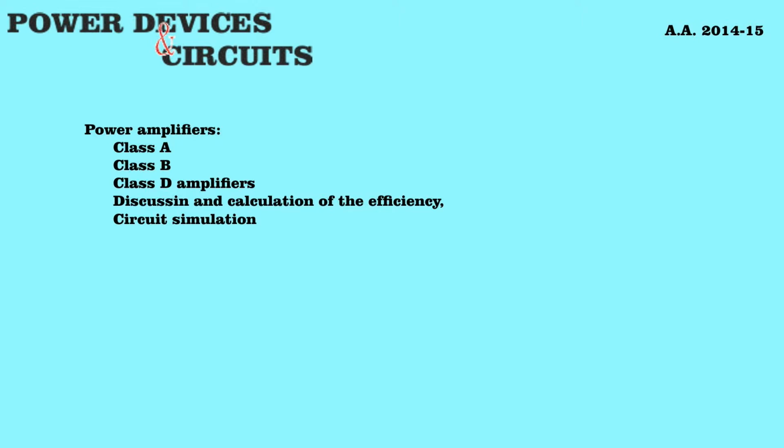These two power dissipations: for the negative voltage power supply it is just the supply voltage multiplied by the output current, zero current, while for the positive supply voltage is more complex, but it's quite simple because I multiply the voltage by the integration of the current, that is the collector current, divided by the period. In one period this current will be just I0, because it will be I0 plus one sinusoid. The sinusoid in one period is 0, and this is the result.